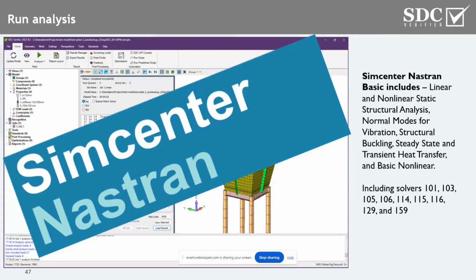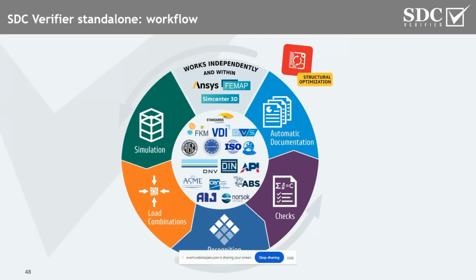And when it comes to analysis itself, SDC standalone is based on the SimCenter Nastran solver that supports various different types of analysis, starting from linear and non-linear static analysis, ending up with more standard ones, like for example normal modes, buckling analysis, and so on. So basically here, you end up with the first two steps effectively.